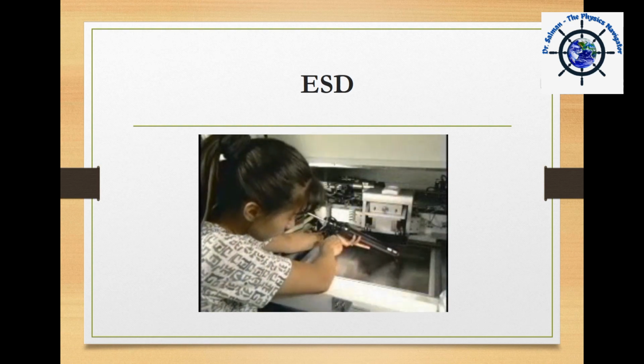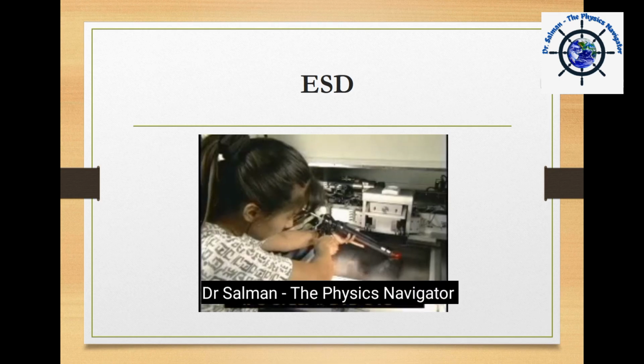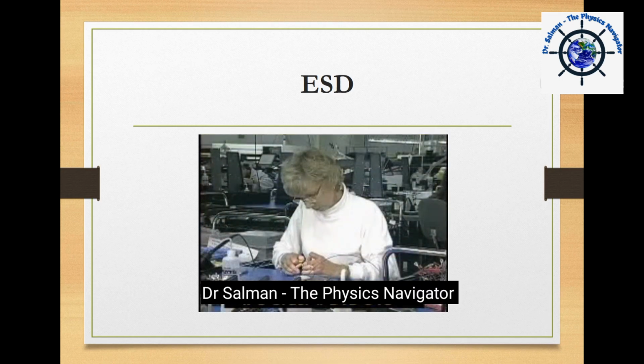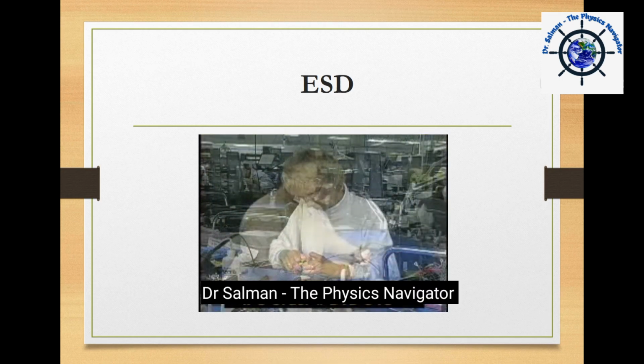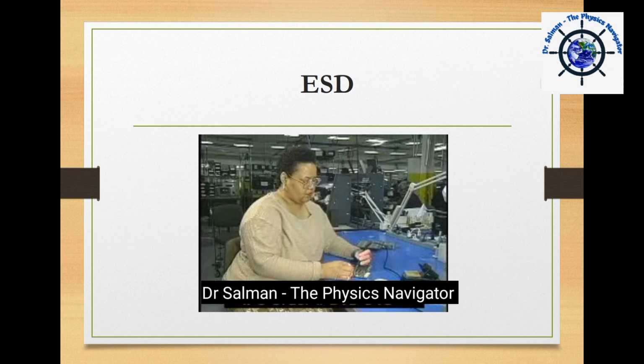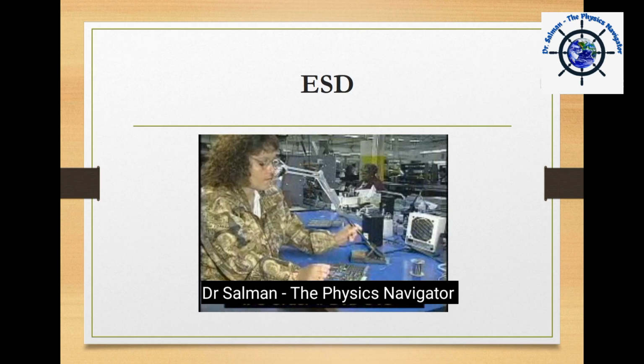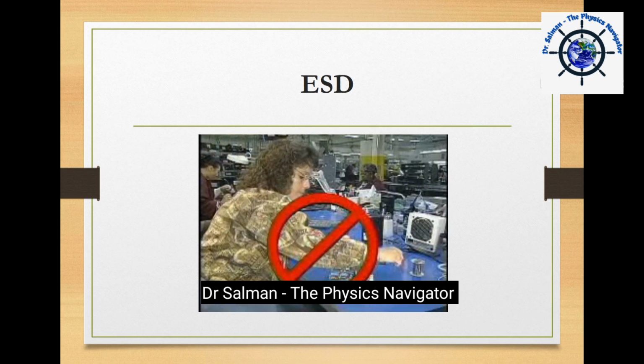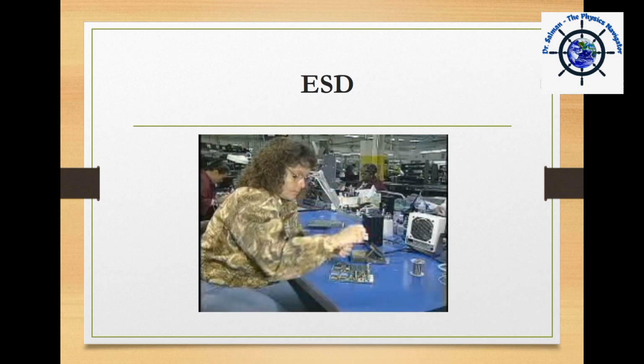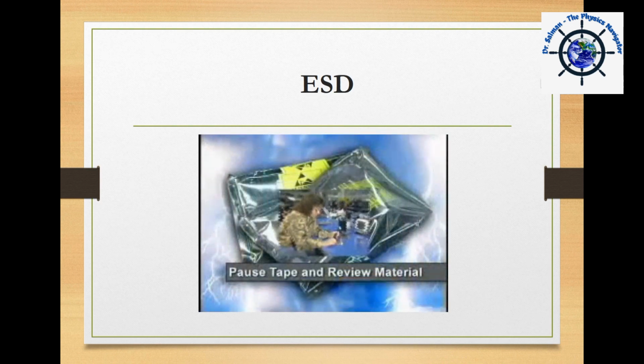When conductive smocks are not provided, you'll need to be aware of what you're wearing. Clothing made of cotton, rather than wool or synthetic materials, will help control ESD. Also, you should avoid wearing loose clothing that drapes down and may come into contact with ESD-sensitive devices.